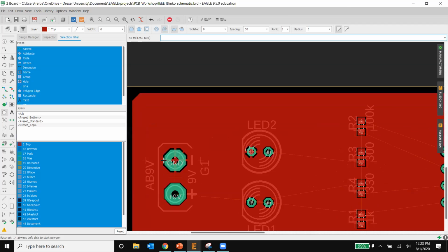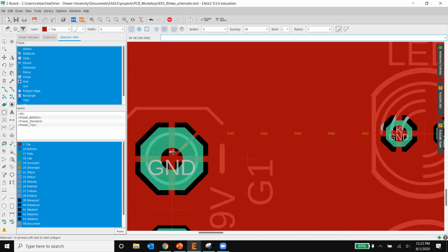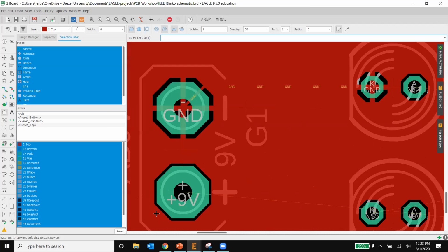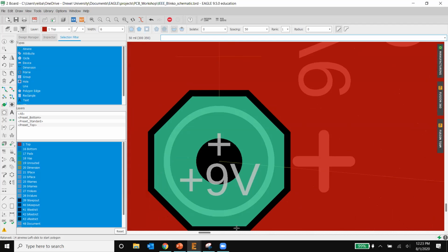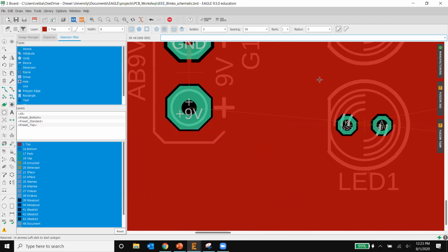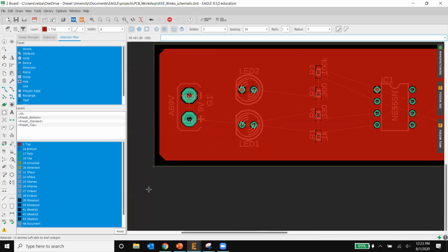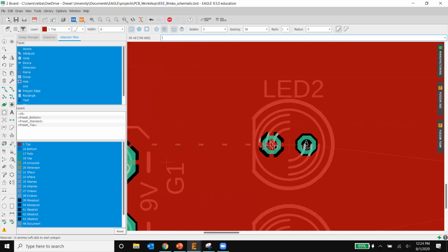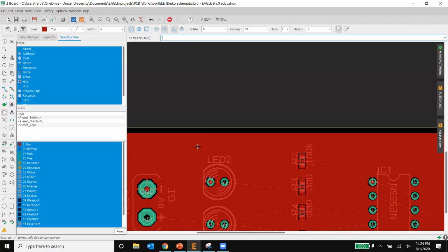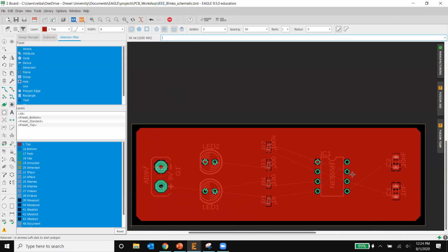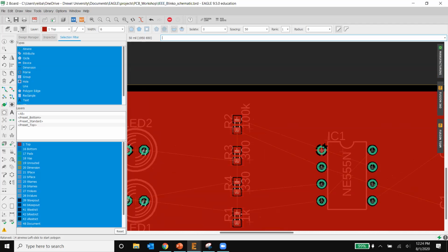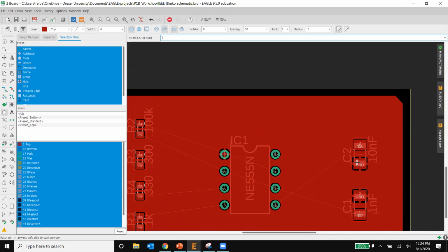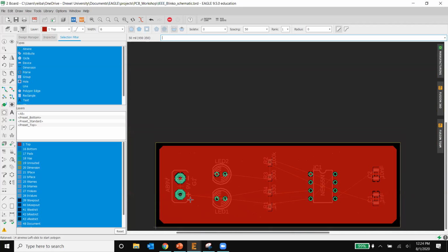But what do you see here? Do you see this big red X? That means that there's a thermal connection there. Here you see that there is no thermal connection there. So what this is saying is that from the negative pole of the battery, it's going and connecting where it should be, right? It's making a whole sheet that's going to be ground for you, right here, ground here, and ground, and ground. It's telling you what signals are, and it's very nice.